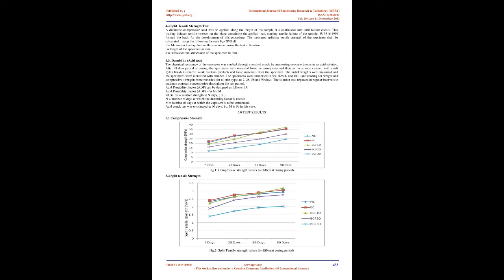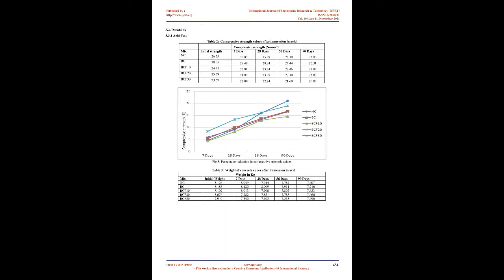Once the concrete hardens, the water supply is cut off, and the bacteria become inactive and remain dormant till there is any further supply of water. Hence, it increases the strength of concrete and also repairs the cracks formed, protecting the structural integrity.